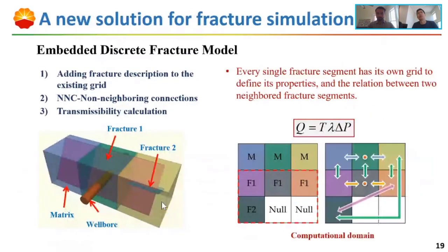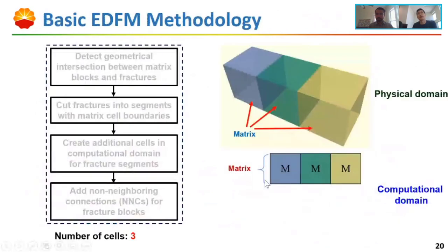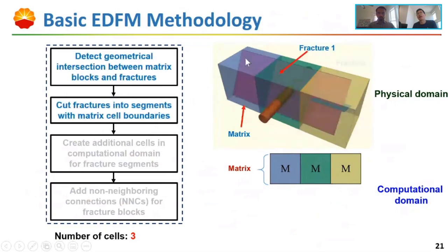So we are always looking for some new approach to get better fracture simulation results, which is why we developed this embedded discrete fracture model, which is EDFM. In this method, we can make every segment of the fractures have its own geometry and properties. Here, in the physical domain, we have the reservoir, and we have 3 grids to represent that physical domain in the computational domain. We also have 2 fractures, 1 large fracture and 1 smaller fracture.